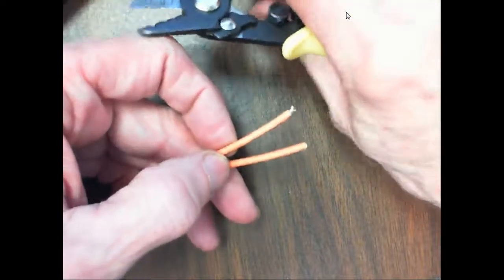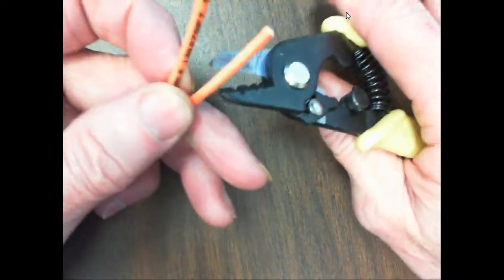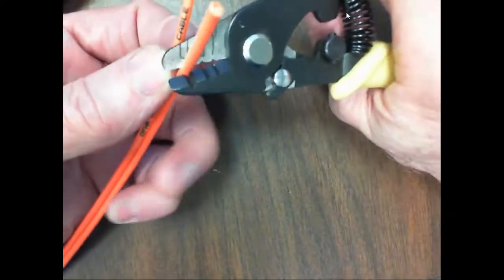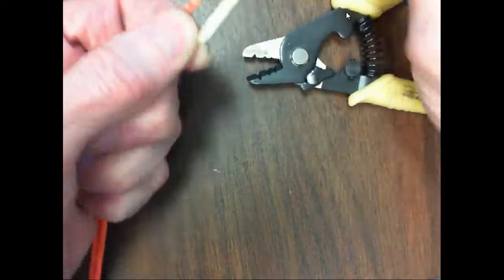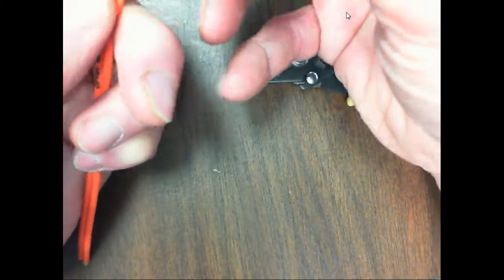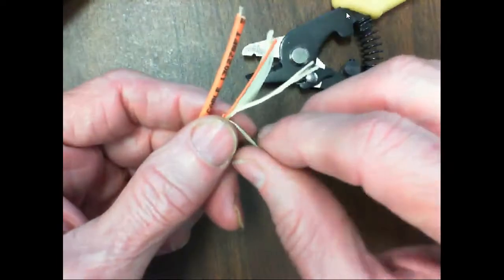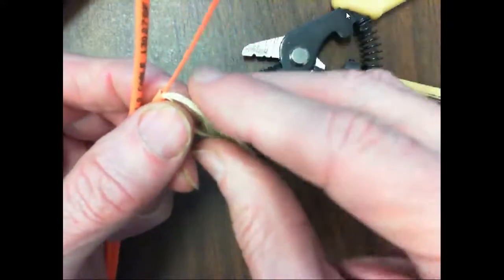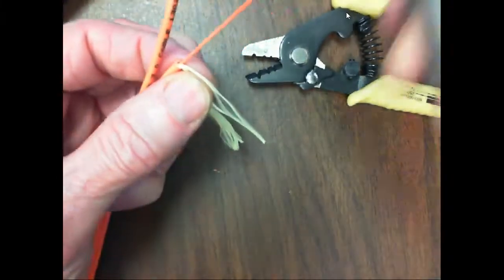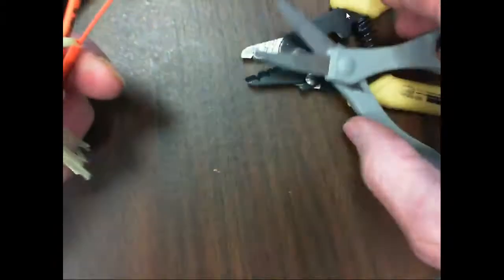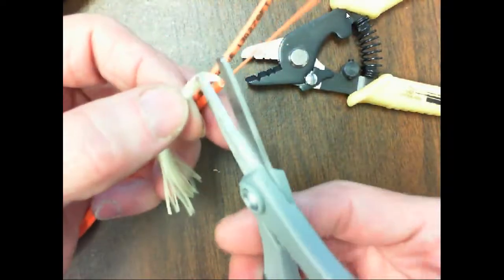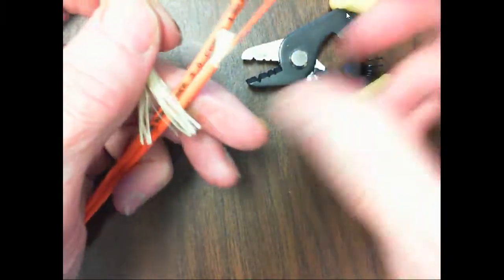This is a stripping tool right here that allows us to strip the whole thing. So this outside one, what we do is we just come up here and just put it like that. Then we pull this off. And then this exposes the Kevlar. You can't cut the Kevlar with regular scissors, so we have Kevlar scissors. I don't want to catch anybody cutting paper or anything with this scissor. So this does a real good job. It's going to be real hard here because I got it so short. But we use this to cut the Kevlar.